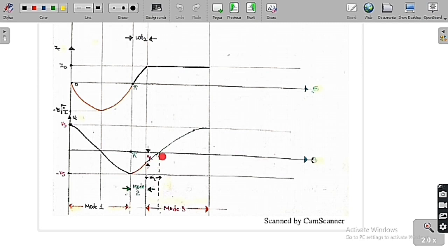Now after this the capacitor voltage is positive. Positive means we can say simply that Tm is now going to face the forward blocking mode, or simply it is already off. So only up to this much amount of time it faces the reverse voltage. After that it is going to increase, and finally it is going to become the same as the supply voltage. So the capacitor voltage is going to become the same as the supply voltage finally, because it is going to get charged.